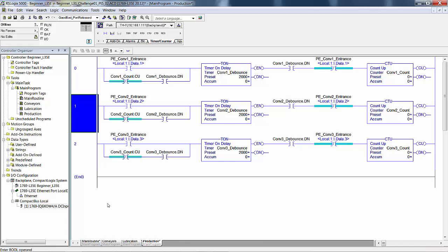If you imagine a carton on a conveyor that starts and stops and jerks, and maybe when it comes off of one conveyor onto another, it tips a little bit. Let's say the conveyors aren't exactly lined up perfectly level with each other. So the carton bobbles a little when it first gets into the photo eye. It could break the photo eye and then tip backwards a little bit out of the photo eye and back in the photo eye. I call that object bobble or carton bobble. Wiggle. Call it whatever flips your switch.